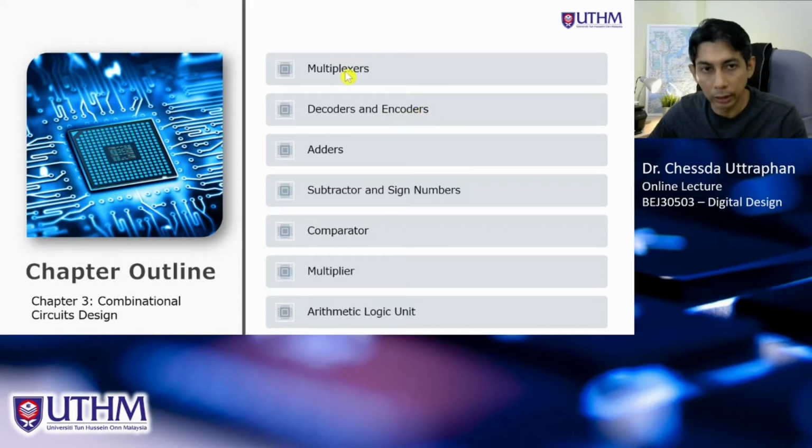Multiplexer is normally used in bus design in computer and in digital hardware, right? For example, we have many wires, and at one time, only one wire must be selected to enter the module or enter the register or whatever. So we need a multiplexer to isolate that output data from the data that we don't want, right? That is the use of multiplexer.